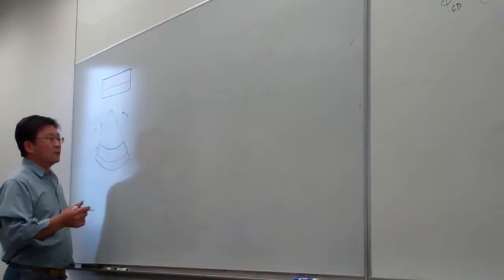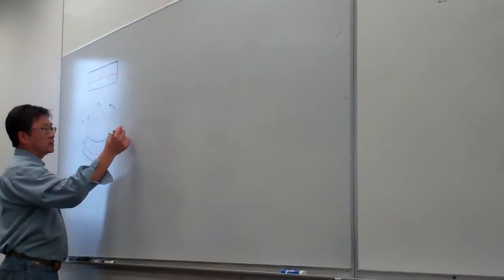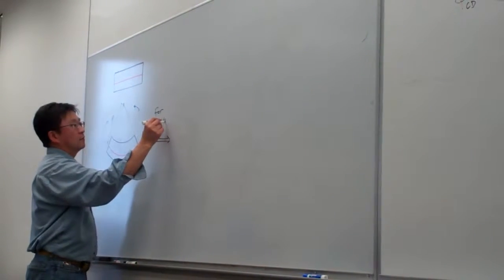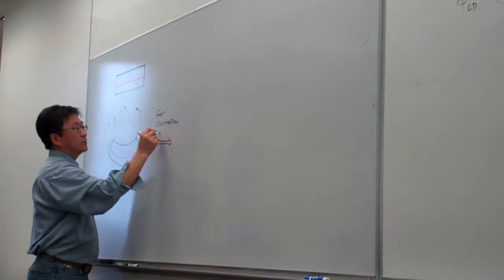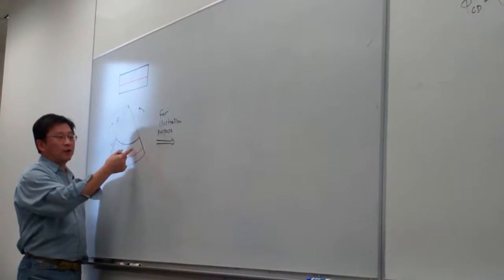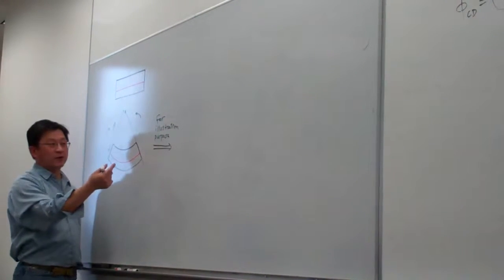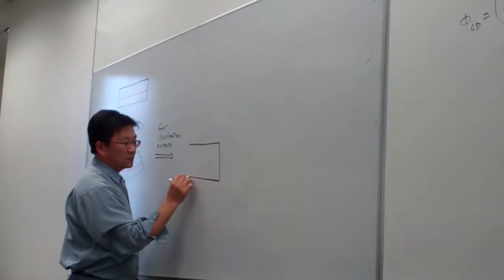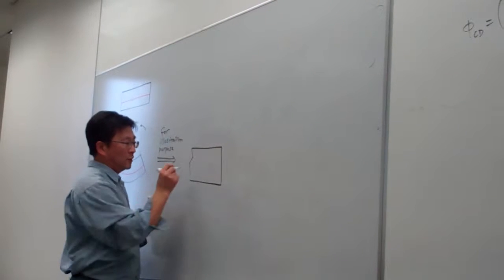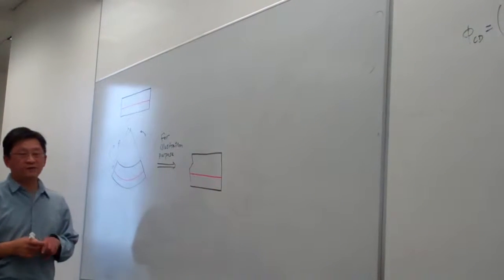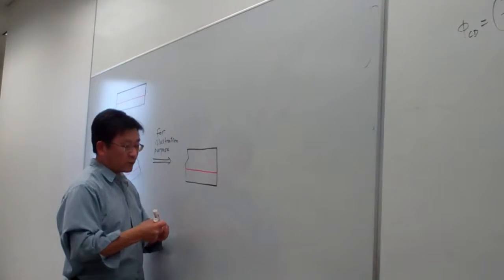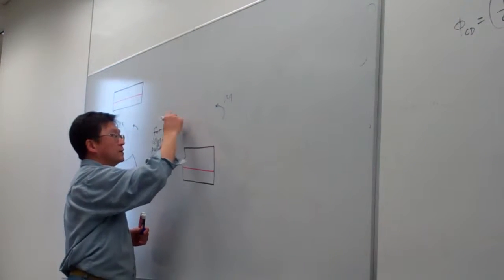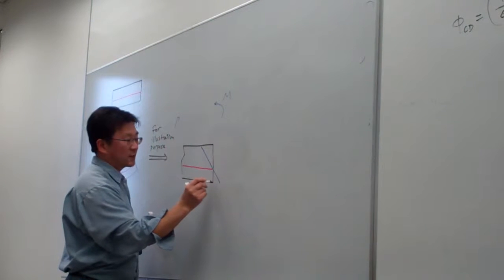And from there, last time we have this. On the cross sections, for illustration purpose, we like not to draw the distribution of the strain on the curve, but we try to draw on the straight. Okay, so hopefully you understand. So that is this specific fiber. And last time we came up with the distributions. For example, if this bending is applied in this way, the distribution of the stress is like this.